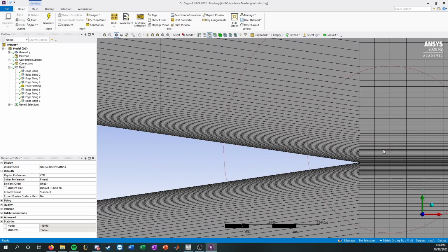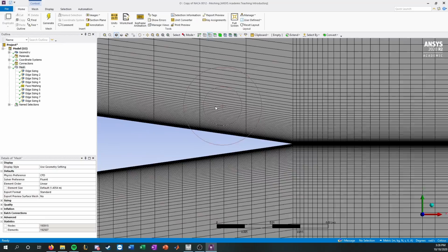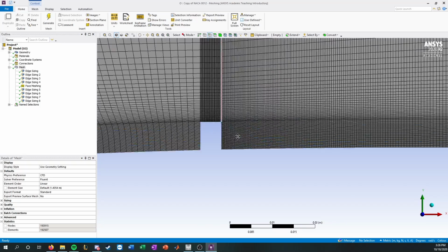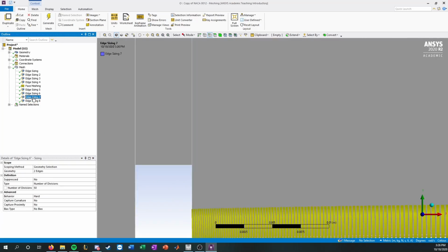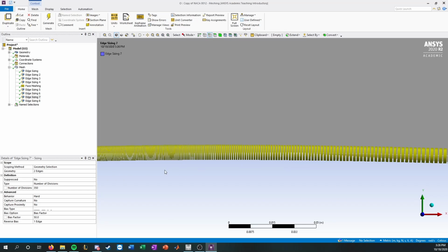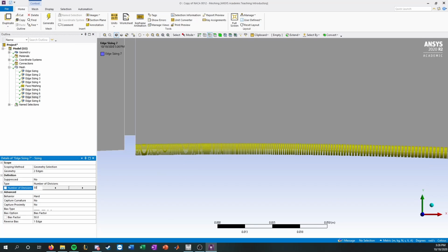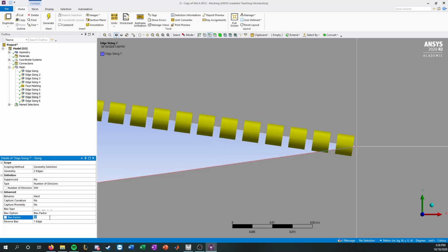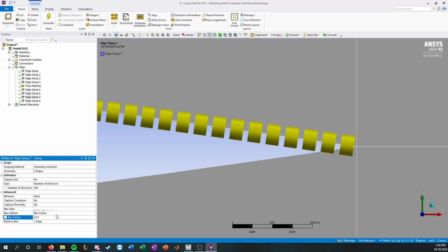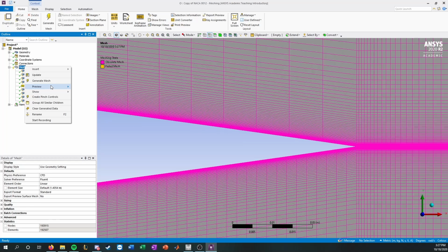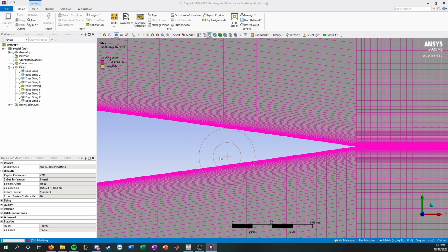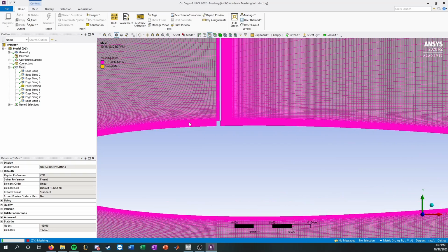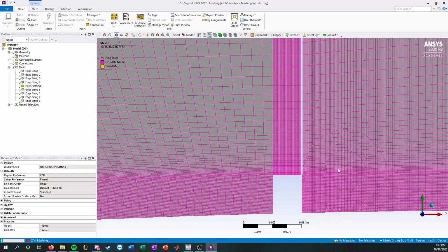Except this is a huge change in aspect ratio. The only way you really could help this is to simply create more divisions. I can add more and more. I can just continue bumping this up. Just make it 500. Let's make it 10. Since I'm adding more cells, I can do less of a bias because I care about this change in ratio. So I wanted small cells there, but I also still want this region to be pretty well defined.